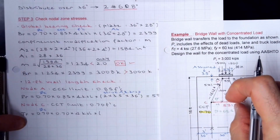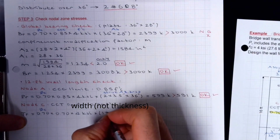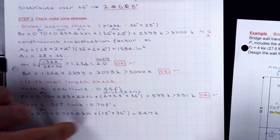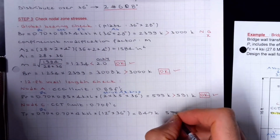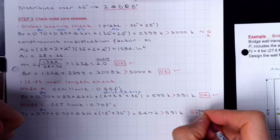In terms of the thickness, there is a lot. Even if you use 12 inches, which is a random number, there is more than that, which is 847 kips. So even if you have 12 inches, which is 6 inch above, 6 inch below, it's going to make this pass easily. 591 kips. So this check, you should definitely omit.